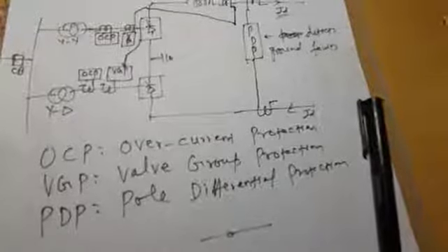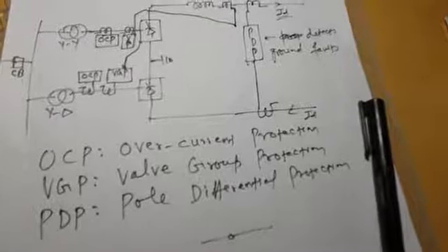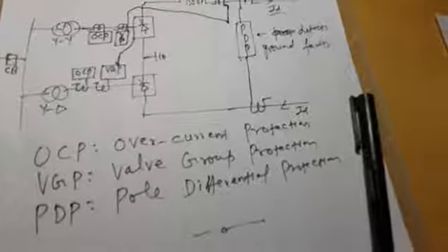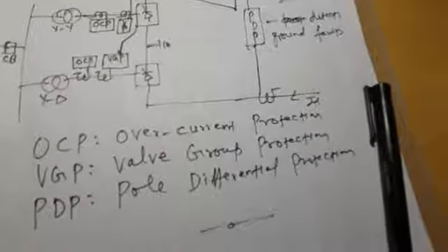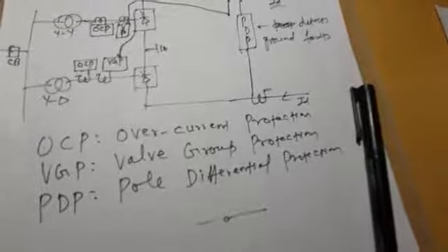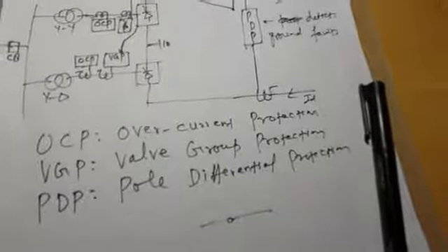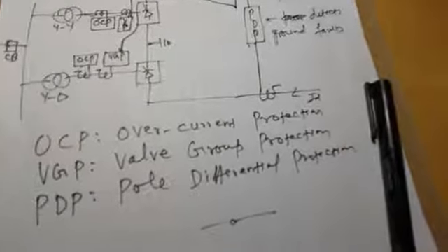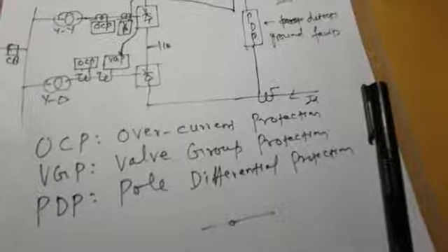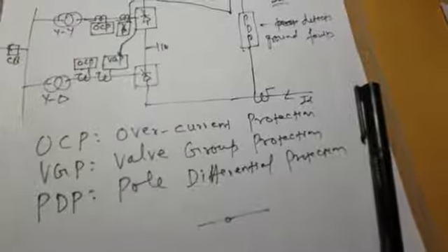Various causes of disturbance on the DC side, which are also responsible for overvoltages in your HVDC converter stations, are a ground fault on one pole, which increases the voltage of the other, unfaulted pole. And then lightning stroke, because your DC transmission line is exposed to atmosphere, and it may suffer lightning stroke anytime.